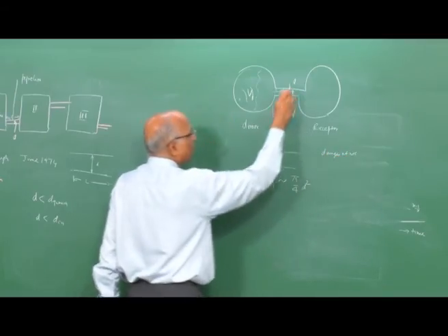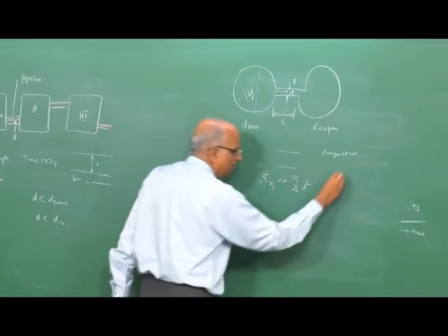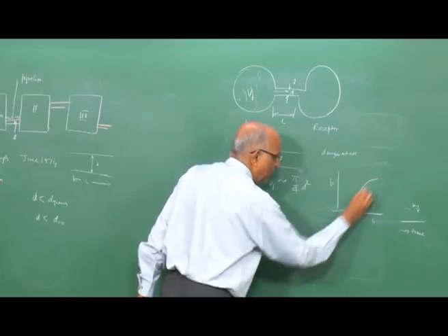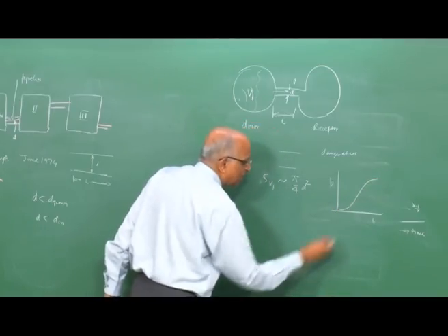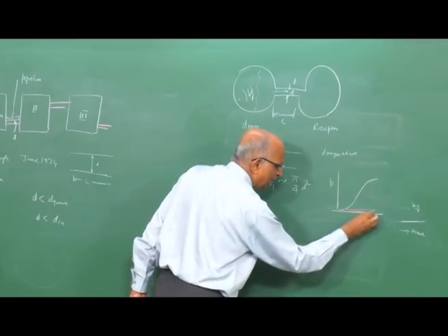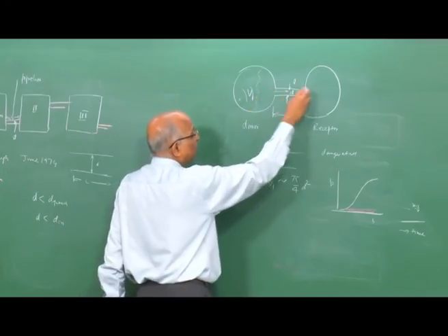But to think in terms of a large vent, and why does it happen? The vent area is so large that before pressure with time tends to get built up, at the low pressure itself it starts venting the gases, and therefore you have something like a gas going over here, and therefore it is an unburned gas mixture which goes out.